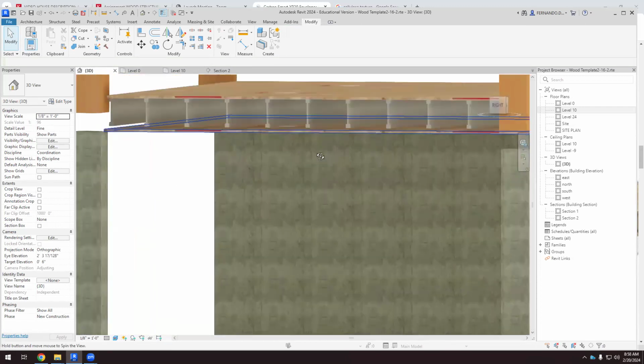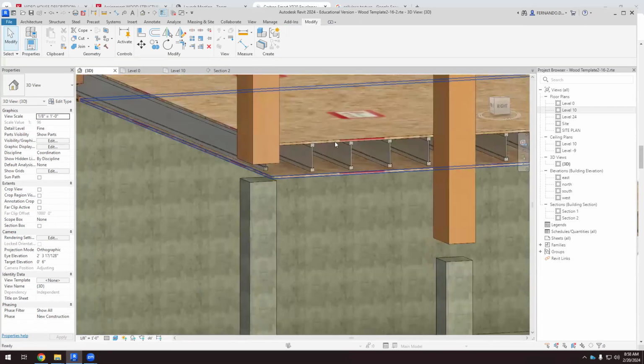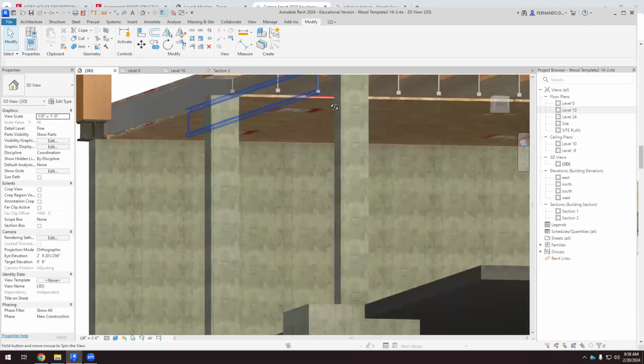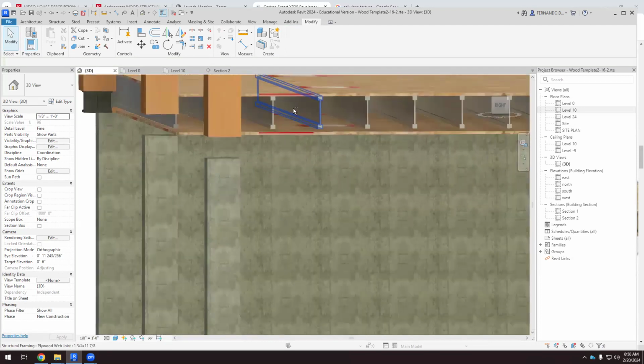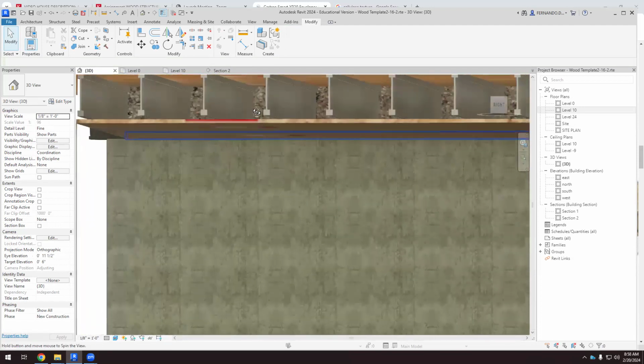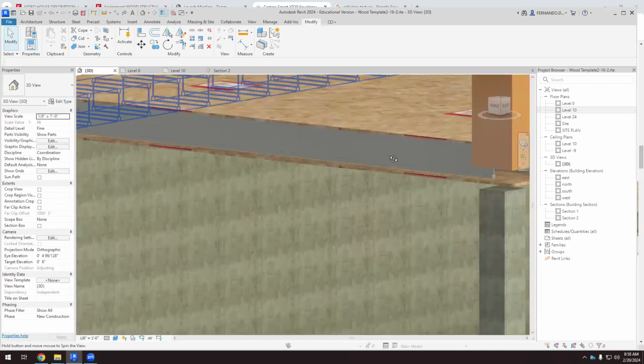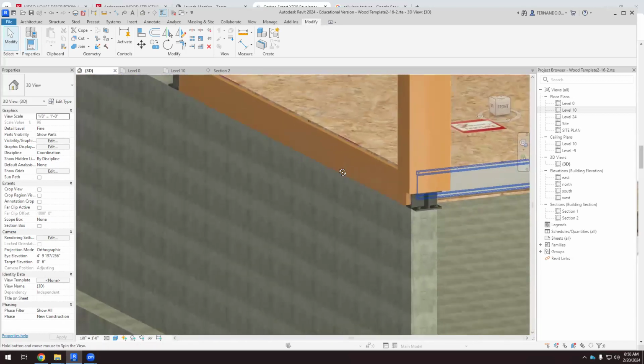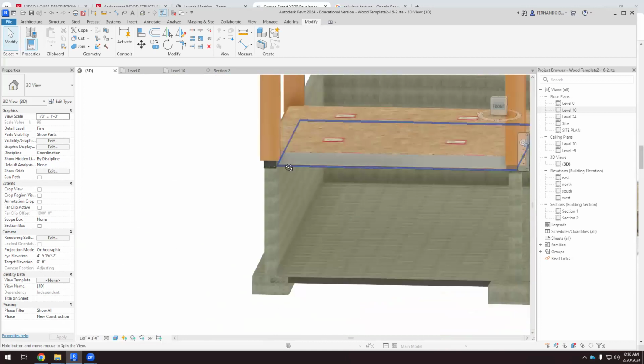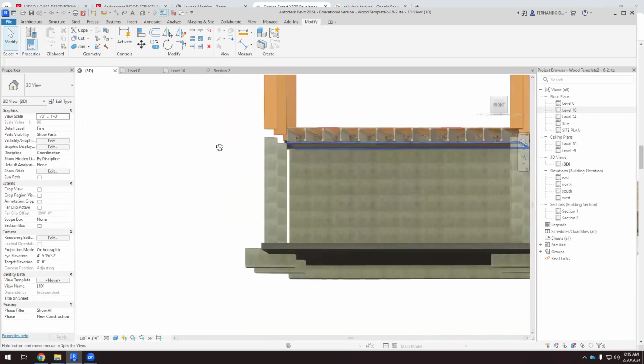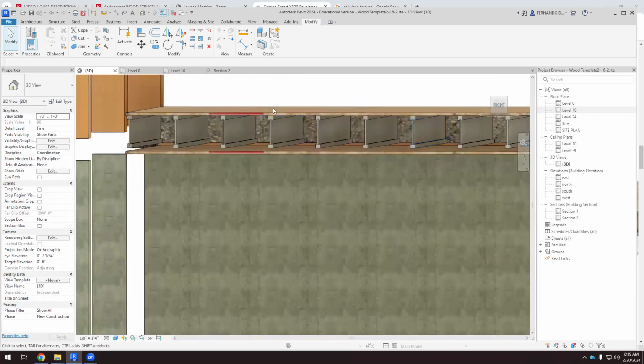Okay, so this is what residential construction is. So we have like a hollow slab made of joists. I have some thermal insulation when I get to the wall so that I don't have a thermal breach here. But that's it. Okay, so it's very cheap, very light.